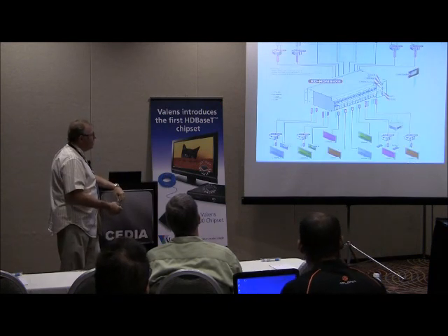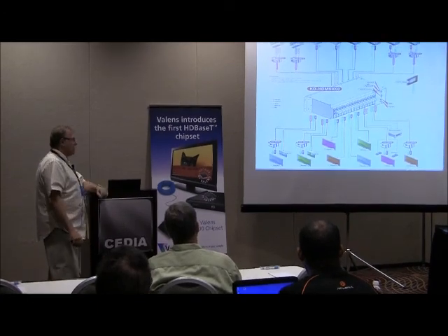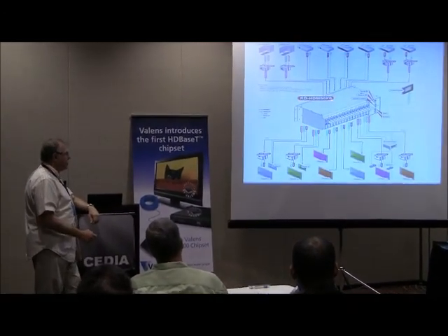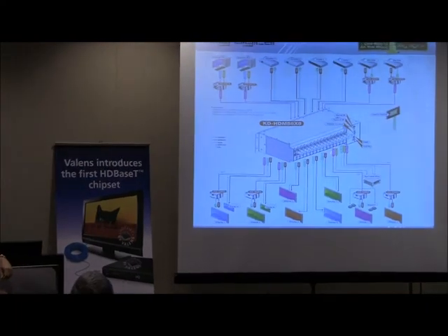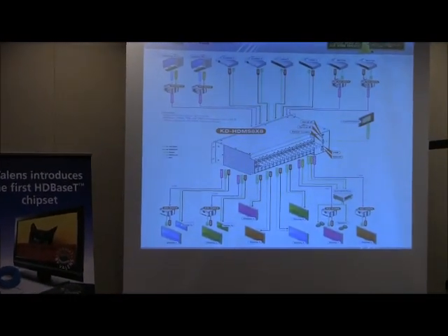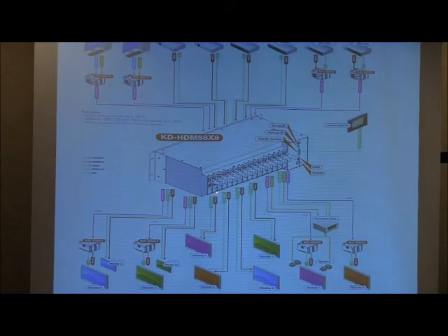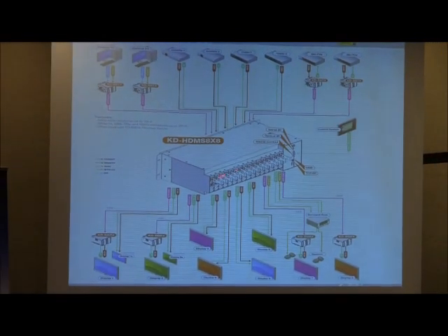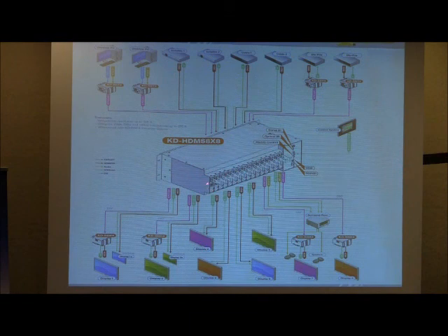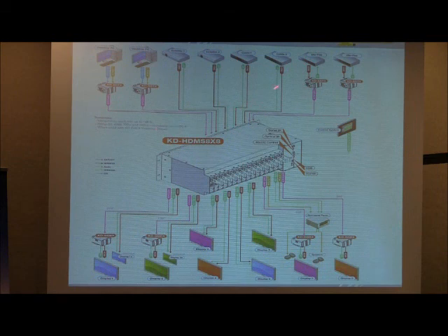So this is an example of our matrix switcher that we call HDMI 8x8 that integrates together Cat5 connectivity and HDMI switching. What we do here is that each input, it's a 16-base slot, has both HDMI and Cat5/Cat6 input, and if you have 8 input devices and 8 displays, it allows you to integrate a variety of configurations on the input devices.